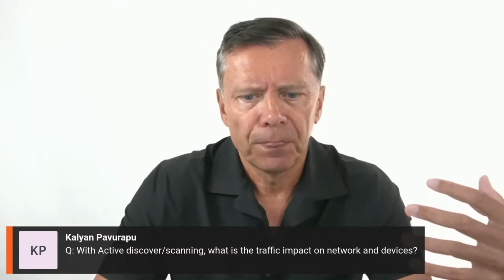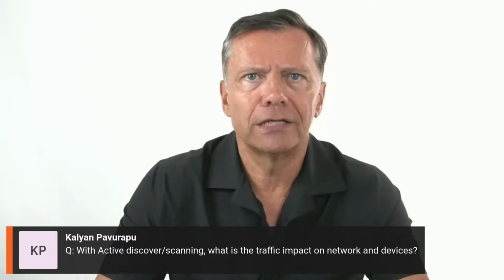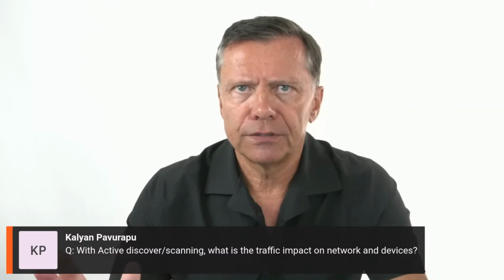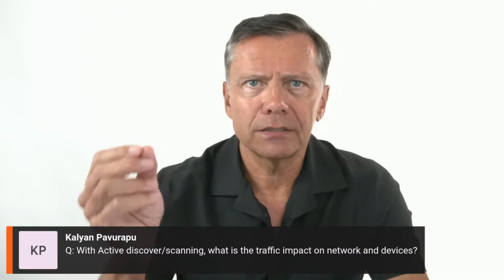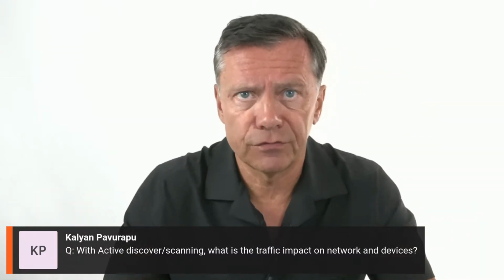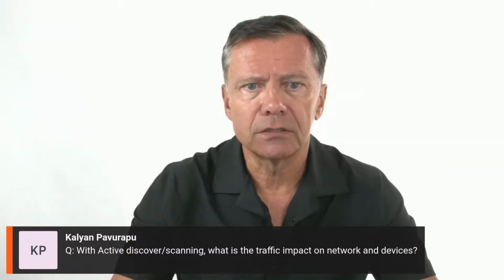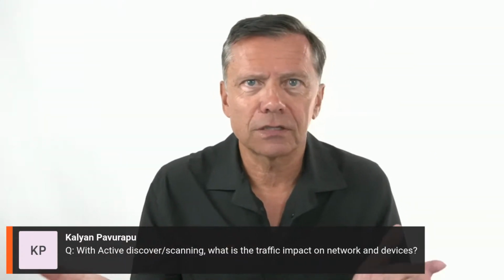Very simple, because OTbase leverages the legitimate industrial protocols that usually the engineering software also leverages, okay? And as a part of these protocols, you have functions that are exactly there for the purpose of soliciting metadata from the device: make and model, hardware version, installed firmware version, connectivity, etc. This is all implemented in those protocols. And since there are dedicated function calls for this, the interactions with the device, that's a couple of seconds.